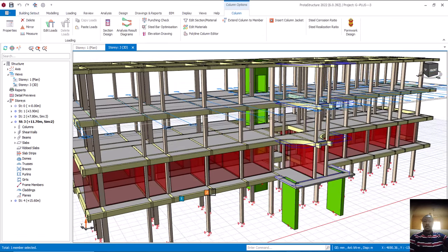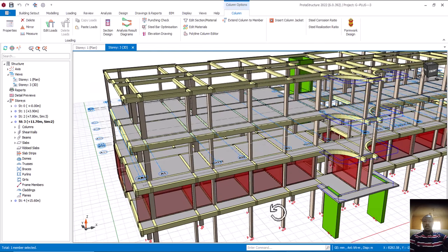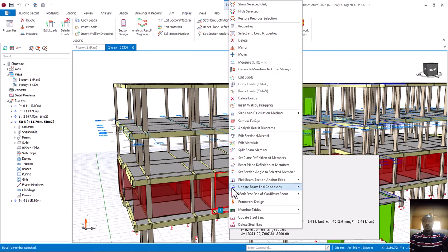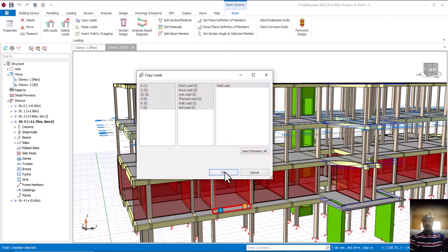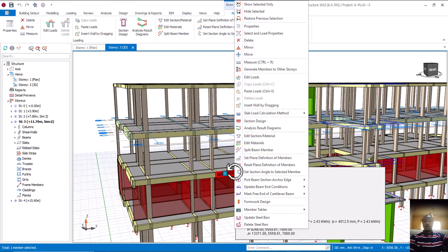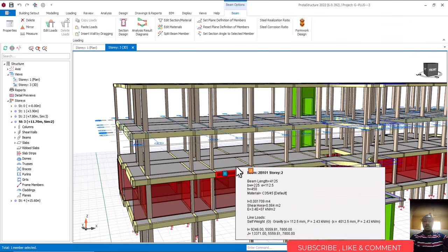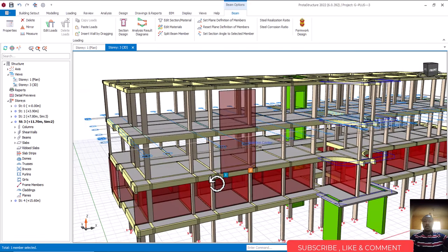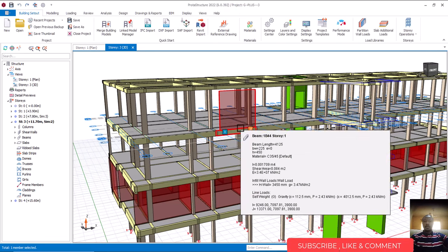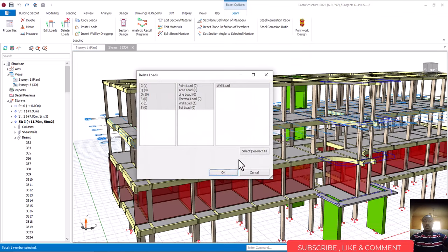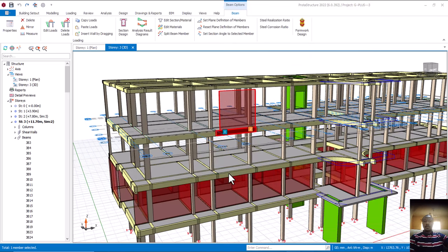Alright. So now let's see what will happen. Let me put my load now. We already have this wall calculated. Click on this, right click, and click on copy load, because it's the same thing with this height. Is that okay? So I'll now click on this one, right click, and click on paste. Okay, can you see what has happened? Let me undo it so you can see what has happened. This one also is taking effect on that particular beam at the upper side.